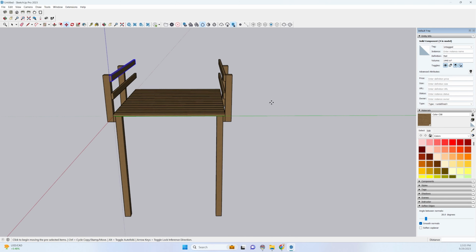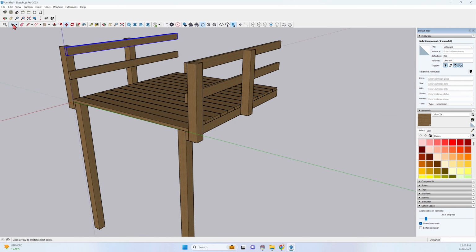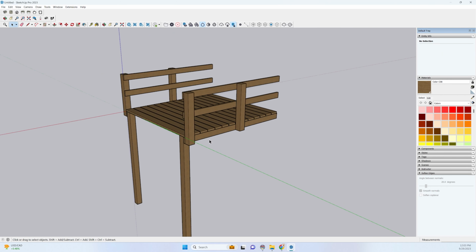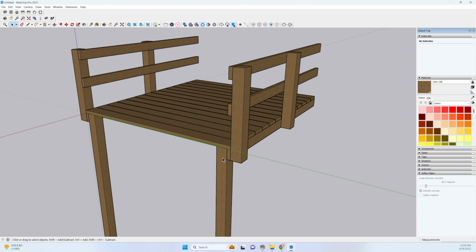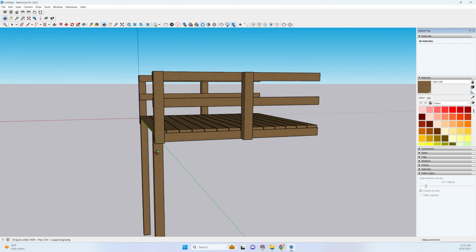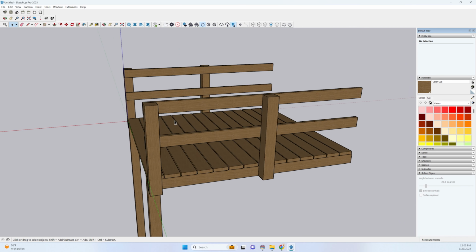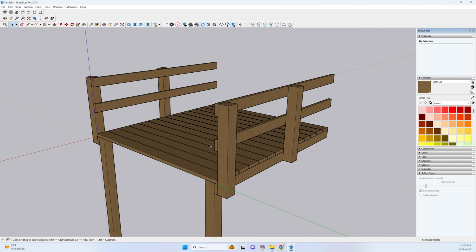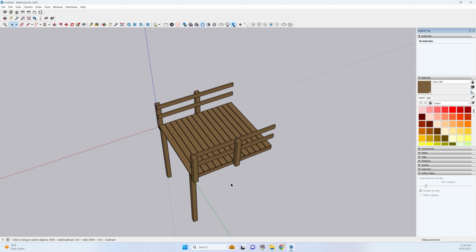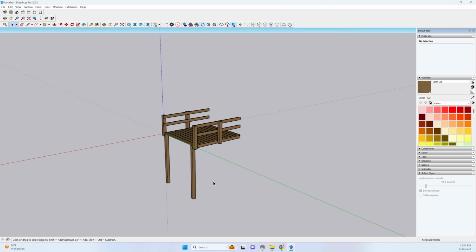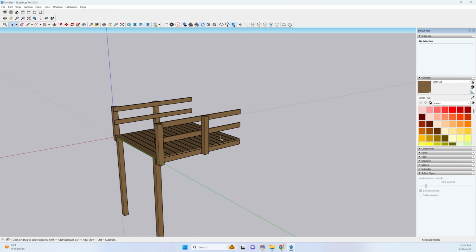There we have it. There is the 10-foot long segment with the deck boards. The substructure is basically 10-foot long side joists and posts, which will repeat every 10 feet. And then I've got 10-foot long railings with rail posts that will be spaced every 5 feet. So again, I'm just looking to create the single repeatable segment of the boardwalk that is a set length here in SketchUp so that I can import it into Beyond Typicals and space it out at that set length.